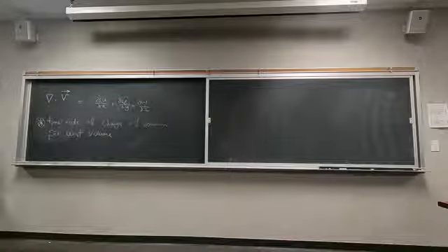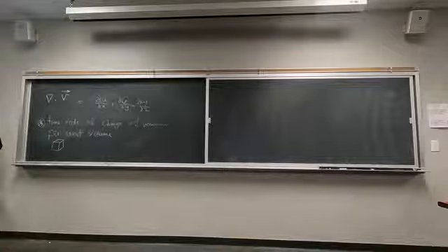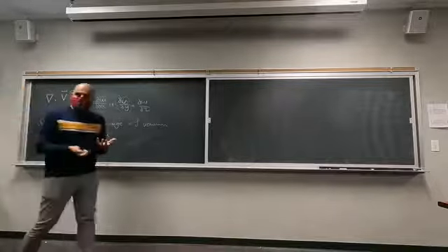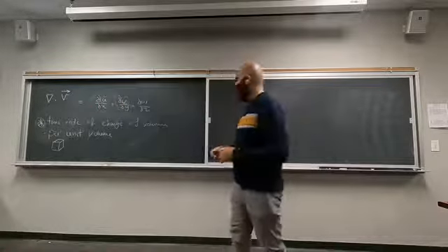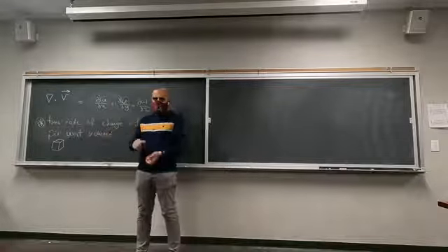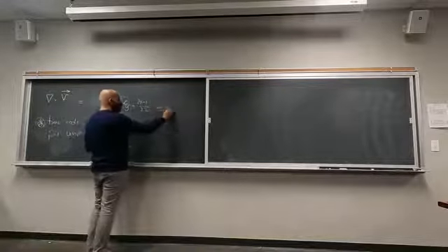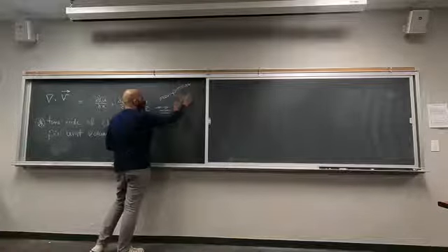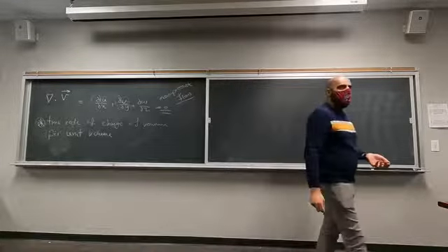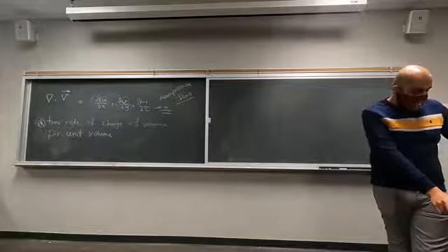So what is the value of the divergence of velocity for an incompressible flow based on this definition? Think of a fluid element. Zero, right? Why? Because in an incompressible flow, the volume of this fluid element cannot change. So the total changes in all of the directions should be eventually 0. So if you're pulling it in the x direction, it actually has to shrink in the other direction, right? To compensate for that change in the other direction. So for an incompressible flow, this has to be 0. Which is a type of flow we are going to see in low speed flights that have Mach number of less than 0.3. Any questions here?